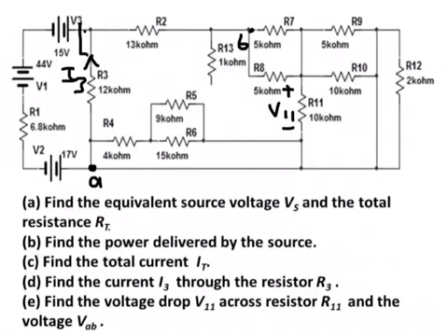So this whole circuit can be replaced, all the resistances can be replaced by one single resistance connected to one single source. This equivalent source, we call it Vs or V equivalent, and the total resistance is called here RT, but it can also be called R equivalent or R input.